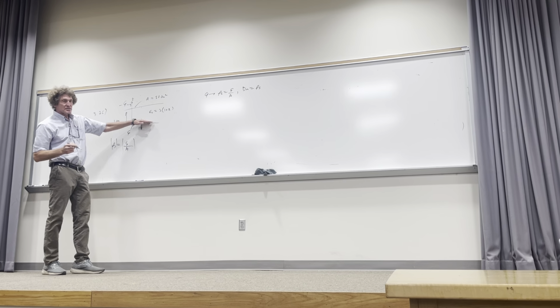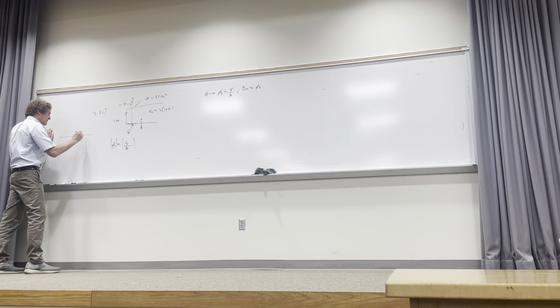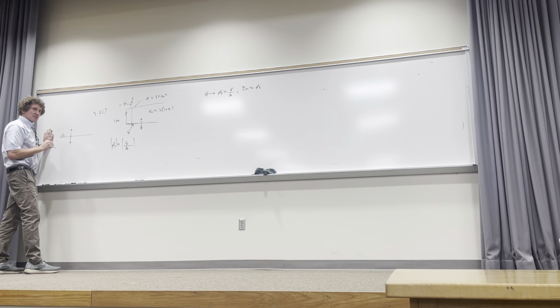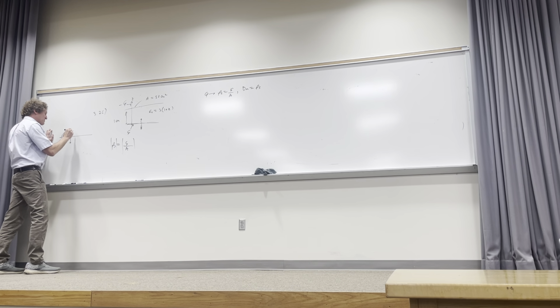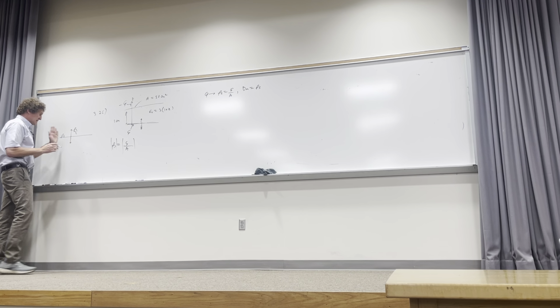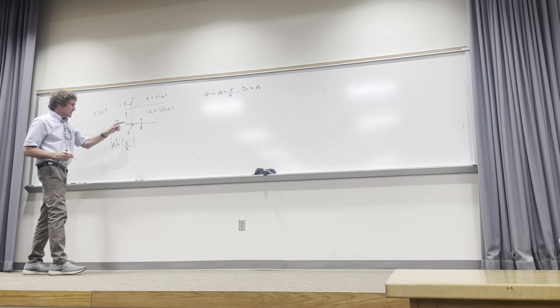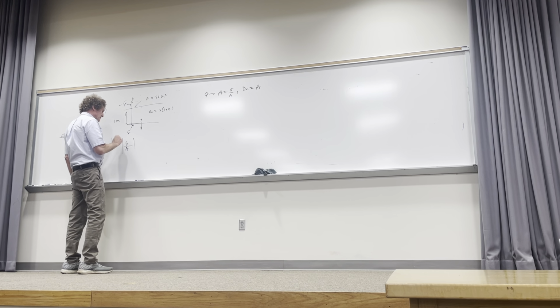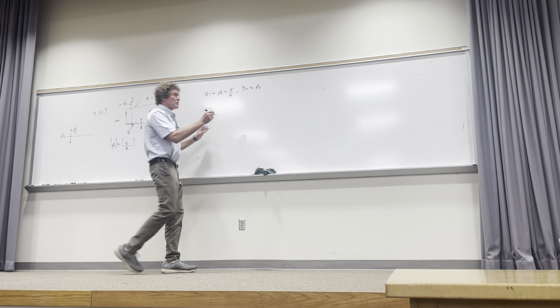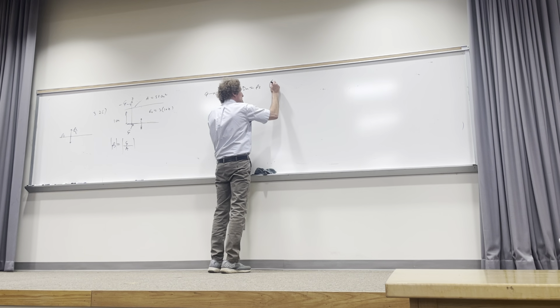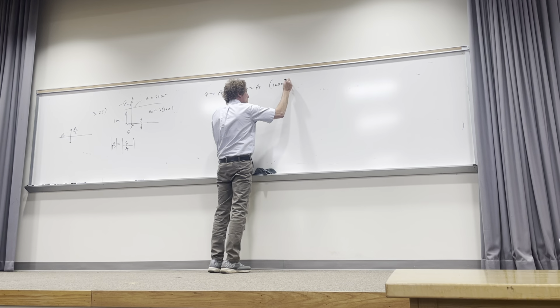And frankly, if you just had a very thin plate where you had rho s on it, the D field in either direction would be the same magnitude, and the magnitude would be rho s over 2, because it's not just a perfect conducting plane where it's only going one way. Does this make sense to everybody? Now, the D field in here will be this value. So this will be rho s, and I should say inside the capacitor.